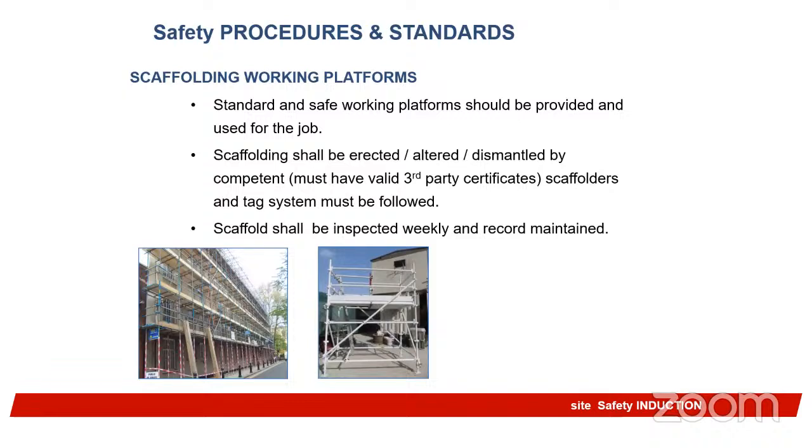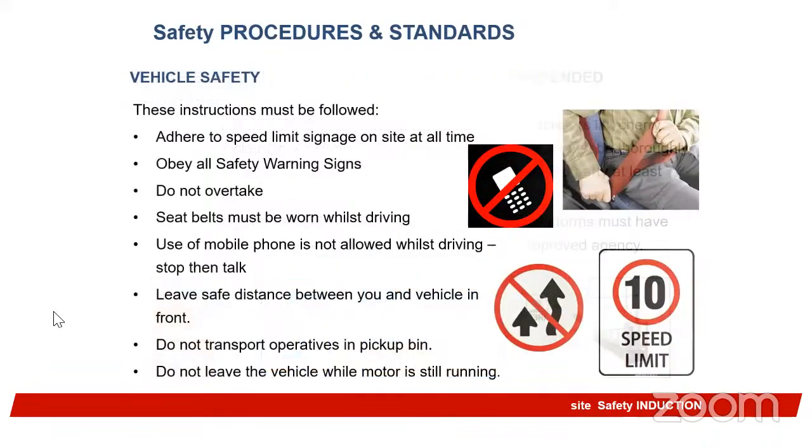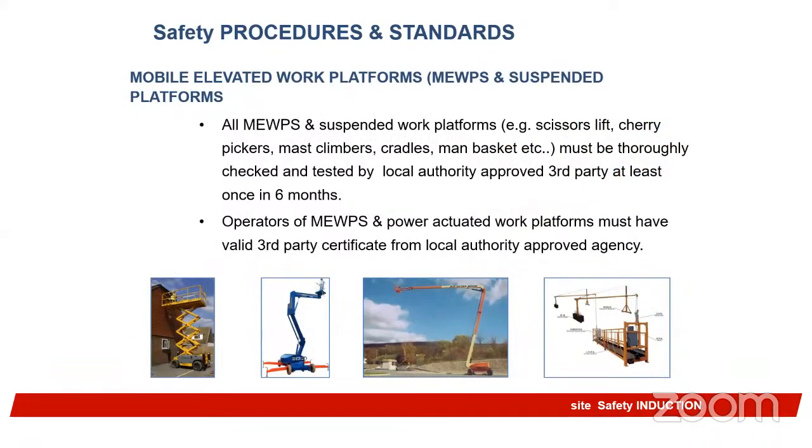There should be a tool board provided. There should be a point where someone can anchor when working at height, and it should be properly inspected either weekly or daily, depending on what is written in your established procedures. Some inspect it daily and some inspect it weekly, as the case may be. But we advise, especially for construction activities, that it be done daily, because every day there's a new hazard, a new risk.